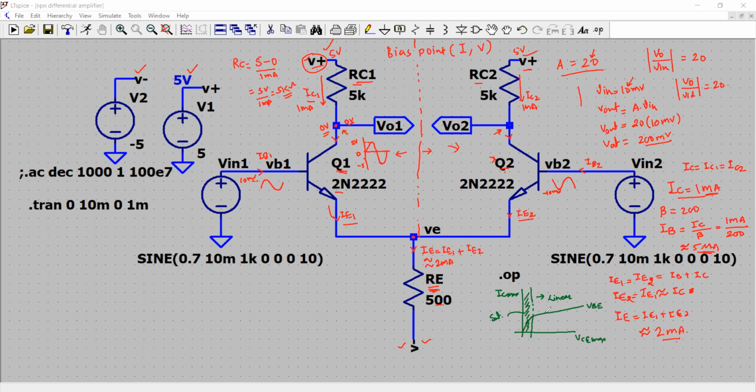For example, you choose this value of the current and voltages. So here is your VCE, and this is the value of your IC. And IC max, from the data sheet or the SPICE model, is about 0.8 ampere, and VCE max, we've seen, is about 30 volt. So you are much less than that value.